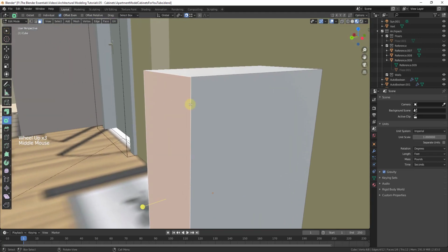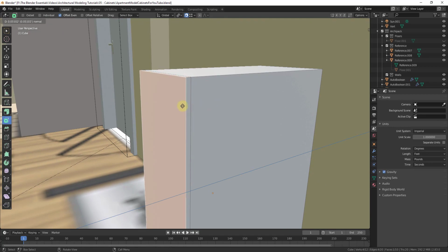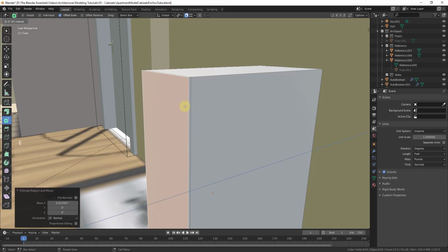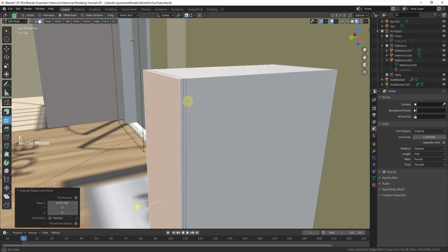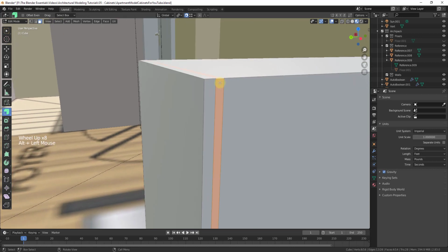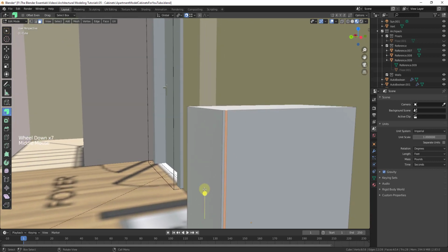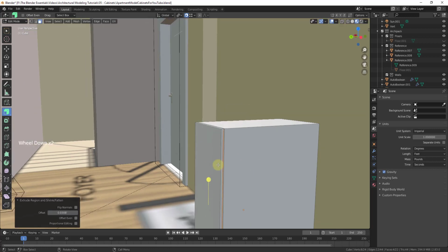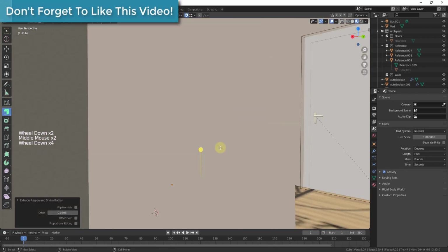Now let's start working on our door. What I want to do is extrude this face out. So I'm going to tap the E key, and extrude it to right here. Then I'll extrude it again the thickness of my door. Once I've extruded this out, I'm going to Alt click to select all of these faces, then click and hold and select the option for extrude along normals. What extrude along normals does is allow me to extrude this in. So I've got a little gap here, like we've got a door on this face. So you can see how we did that.